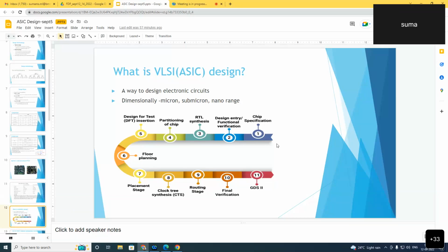Here there are many approaches which are related to front-end HDL based design styles, which I talked about, and which can reduce the power consumption. Also power dissipation has a direct relation with the clock frequency, and dynamic power also depends upon the rate at which the data toggles for a given circuit.